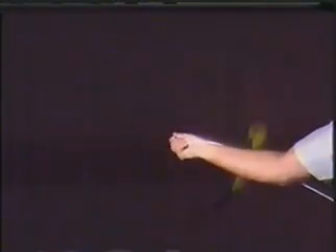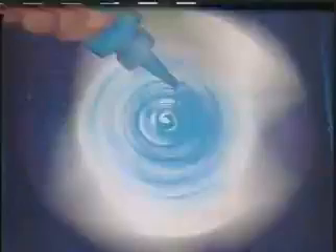We've said that centrifugal pumps add energy to liquid by increasing the liquid's velocity. Let's see how that works. Most of us are familiar with centrifugal force. This is the tendency which pulls a rotating object away from the center of its spin. If you allow liquid to drop onto the center of a rotating object, it will be hurled away from the center. The more rapid the rotation, the higher the velocity of the liquid as it spins out.